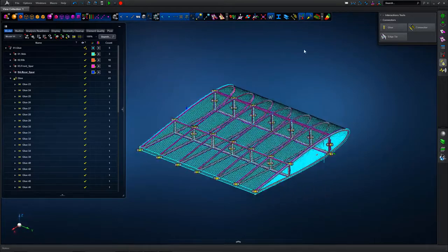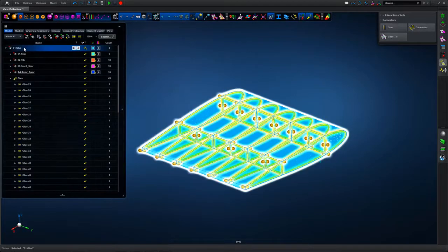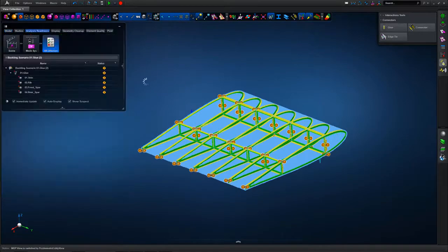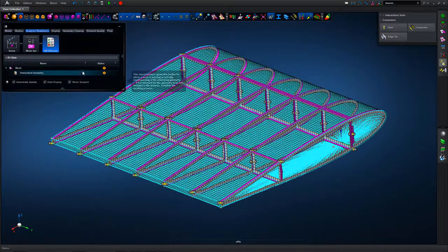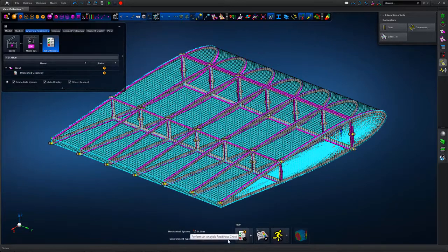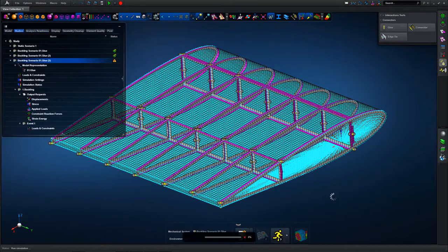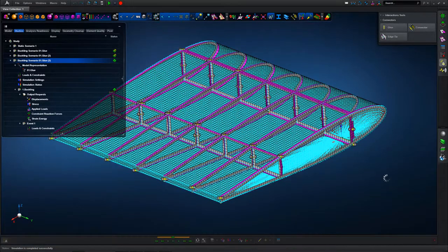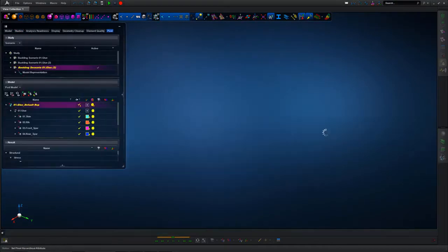So now it's a case of just double checking the loads and boundary conditions, and again, we haven't made any splits on those surfaces, so they're good to go. We haven't needed to redefine any of the material definitions. Again, model ready to run. Only a warning on unmeshed geometry from the original solids we haven't used. Running the buckling case again, and then we should see the model response very quickly, solving in seconds for this relatively simplistic model, just to illustrate the glue technology.